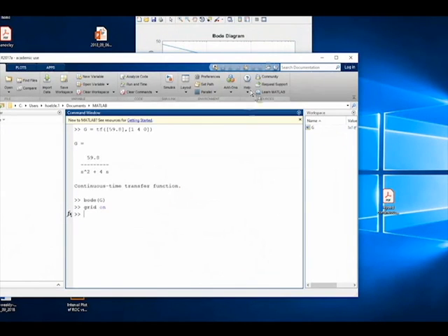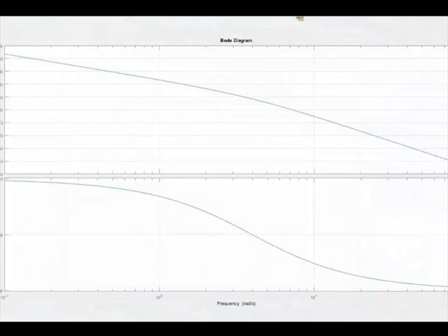Okay, so this is basically what we saw before. This is just the real Bode plot. So it's not asymptotic, it's not an approximation, but we can see the break at around 4 radians per second, et cetera, all these individual features that we saw right here.